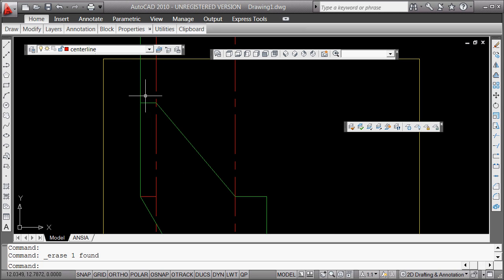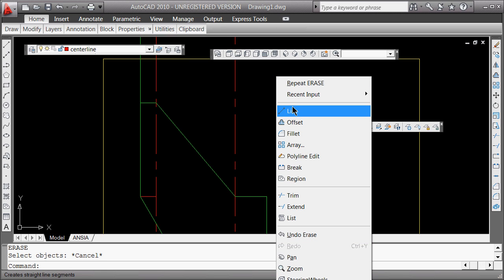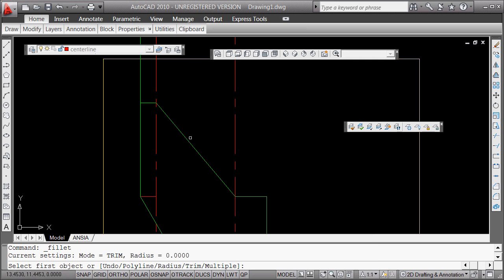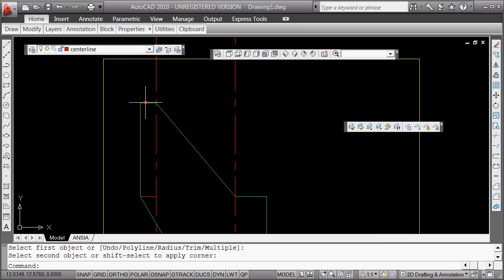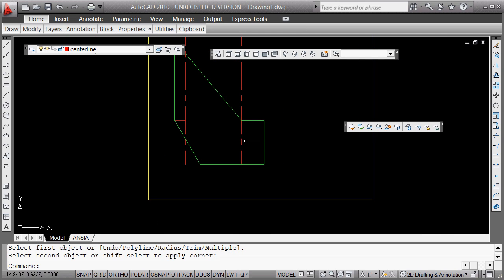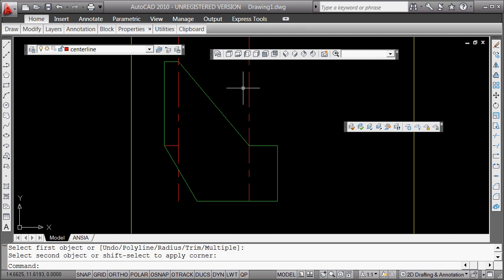We realize this piece here, we didn't fill it correctly, so we can right click, holding down the right mouse button, fill it. Remember, the radius is set to 0, so we can just click, click, and you're good to go. Alright, the last thing we've got to do on this piece before we flip it over onto itself is to figure out where all those holes are.